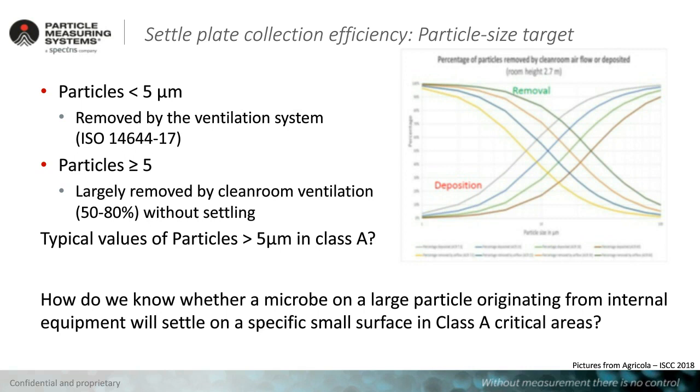And remember, the median of human particles and the median of particles that are microbial carrying particles is 10 microns, and the average shape of a skin flake is typically thin, like 1 to 3 micrometers thin and 10 to 25 micrometers in diameter. That means these particles are the ones of interest that could be considered as risk factors in pharma.